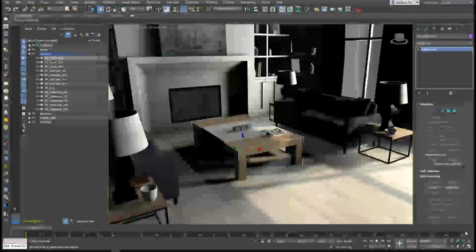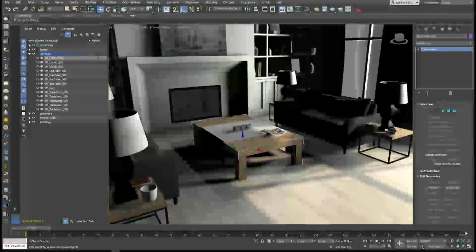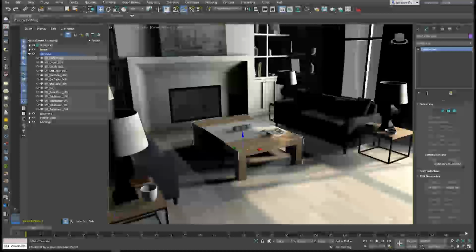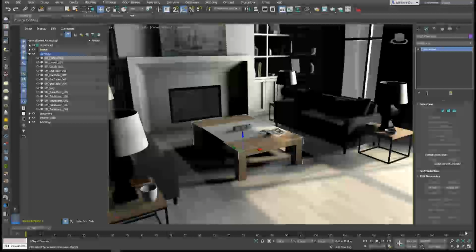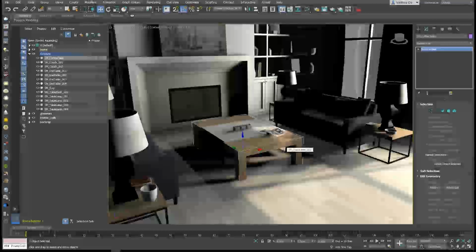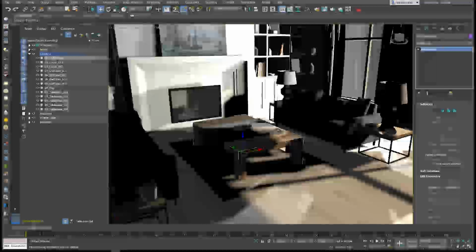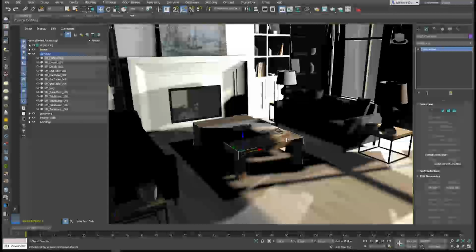The 2 ways we're going to cover to export your data from your 3D tool are FBX export and Datasmith. With FBX Export, assets are exported one at a time. Let's export this coffee table from our previous chapters and take a look at the FBX Export options. Of course, the coffee table is a solid single piece composed of the different shapes. We've gone ahead and attached those together.